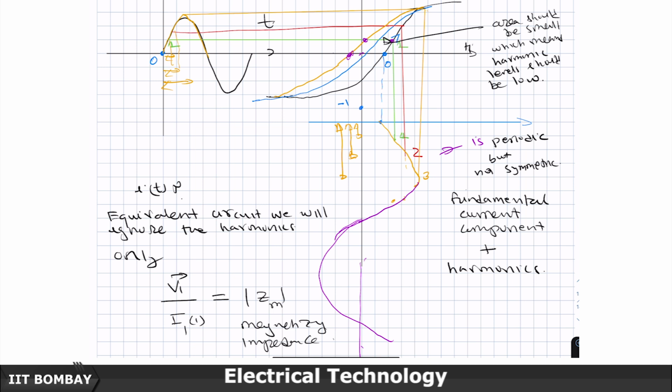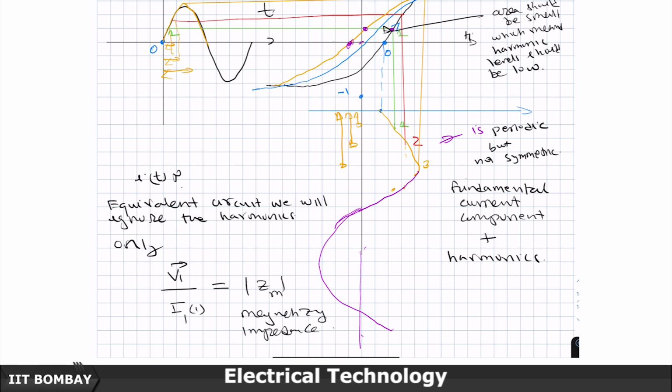The laminations have to be aligned in such a way that the mica strip or the gluing part comes in between the current flow direction, so as to create a larger resistance to it, so the path lengths are elongated and the resistances are increased, and therefore eddy current losses are controlled. Otherwise, there will be severe heating of the iron, and a very lossy device would be created.